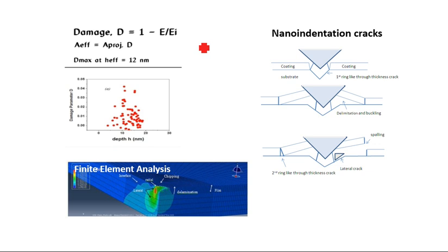So when we are doing the coating, say if this is the surface and we are doing this indentation, there will be an initial high amount of plastic deformation taking place. There will be a change in elastic modulus also with respect to the increased amount of plastic deformation. Ei is the initial value of elastic modulus, and E is the subsequent value that we have obtained.